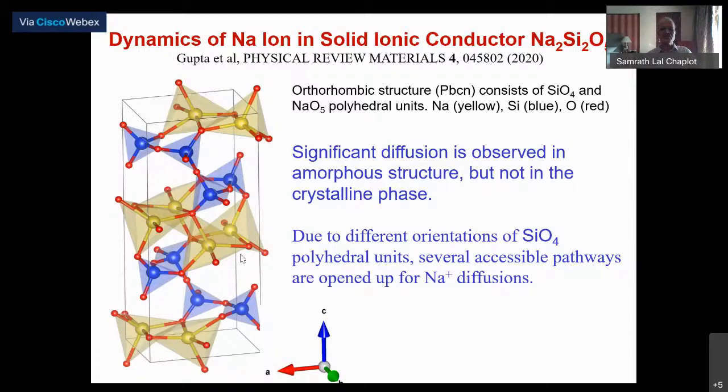And so then you have a liquid structure, and then you deep freeze it, rapidly cool it with a reasonable cooling rate, so that the simulation is still stable. That way, you freeze it down to a very low temperature and you get an amorphous structure, which is essentially a frozen state of the liquid structure, but somewhat relaxed.